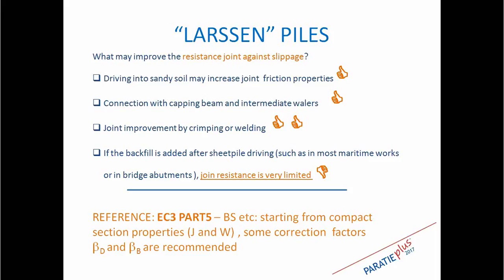The joint between LARSSEN single elements is improved if you drive the elements in sandy soil before doing excavation. In that case, some sand enters the joints, and the joints can be prevented from slipping. But of course it is very difficult to calculate how much the resistance is.